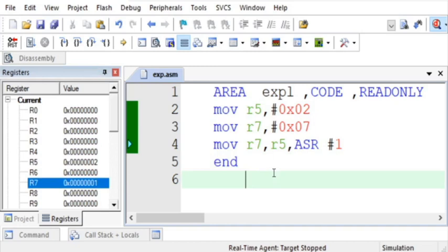That is because if I write this 0 2 in binary, this is what is stored in R5. What is stored in R5? It is starting with the MSB byte is 0, not MSB bit. Okay, MSB byte is 0. If the byte is 0, the MSB bit also is 0. Why? Byte means it is 0 0 0 0. So the MSB nibble is 0, so the MSB bit also is 0.